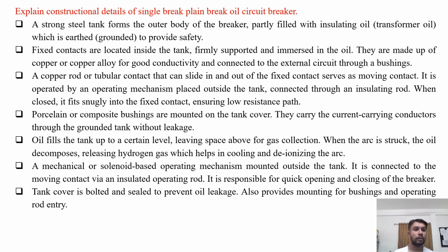They are made up of copper or copper alloy for good conductivity and connected to the external circuit through bushings available on the outer body of the top cover. A copper rod or a tubular contact that can slide in and out of the fixed contact serves as the moving contact. It is operated by an operating mechanism placed outside the tank, connected through an insulating rod.